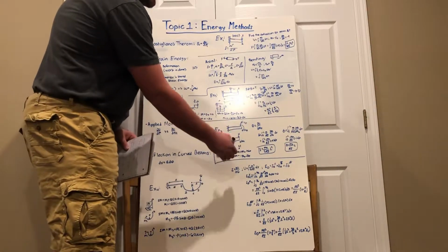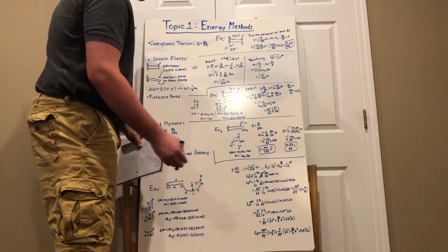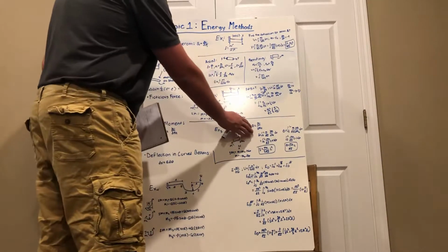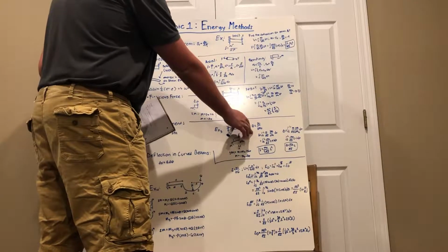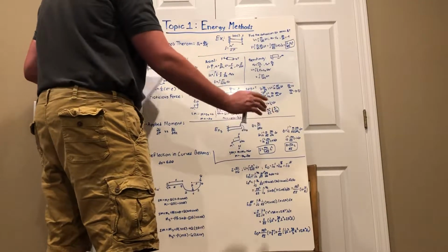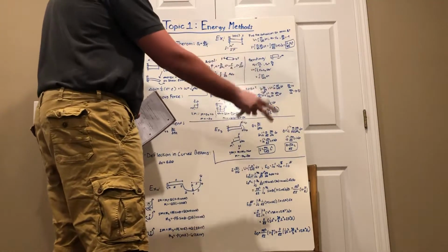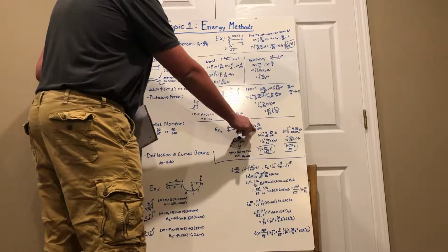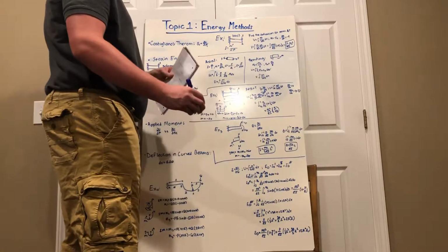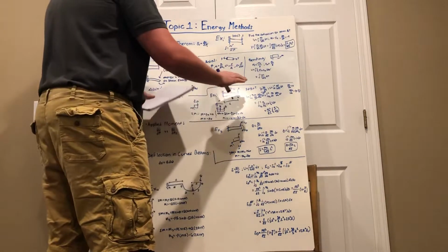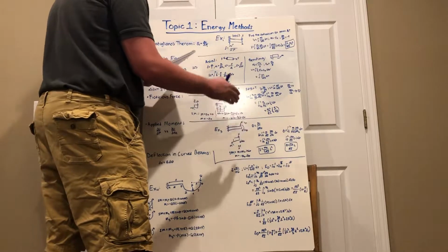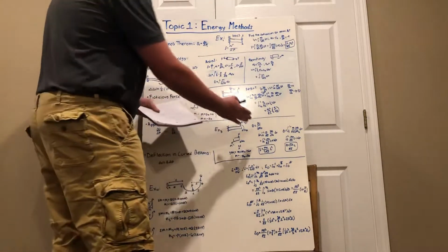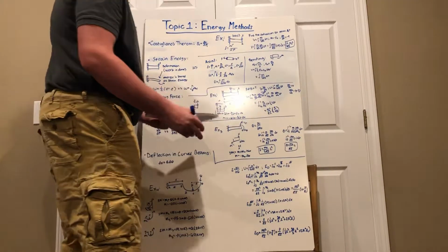Rearranging, we get M equals negative M naught minus Qx. All right, so in this case, let's look at this. Here we're defining theta as our deformation, so we're looking for a deformation angle, which is why we're given it when we're doing moments and taking the partial derivative with respect to a moment instead of the force. We're going to be given an angle instead of a distance in deformation, which is very similar. You basically just do this and you're finding an angle instead of a force.